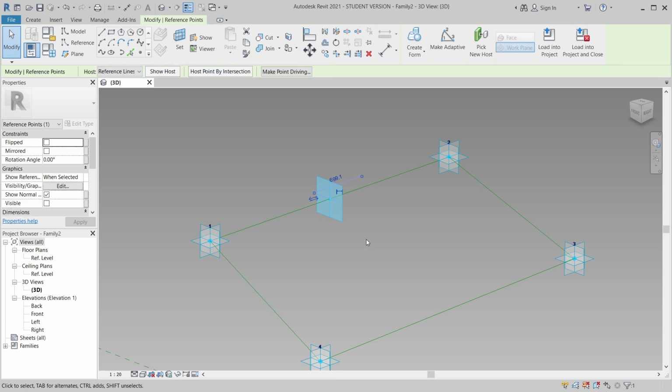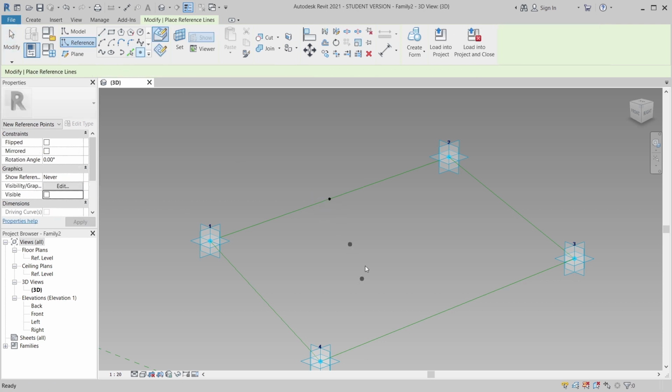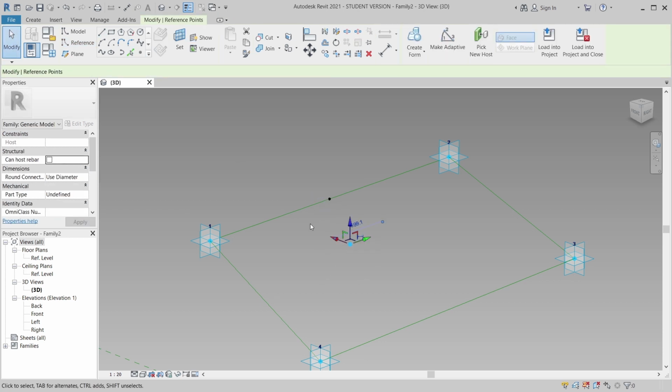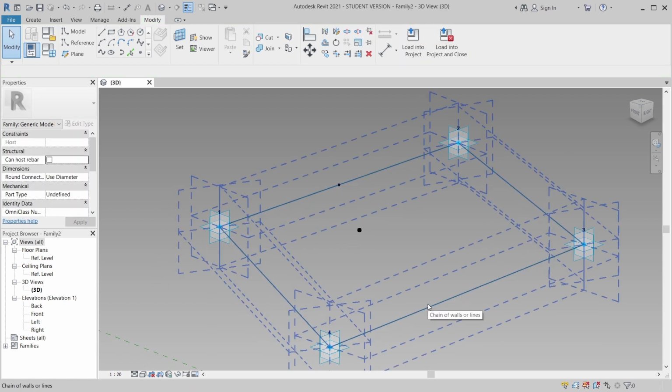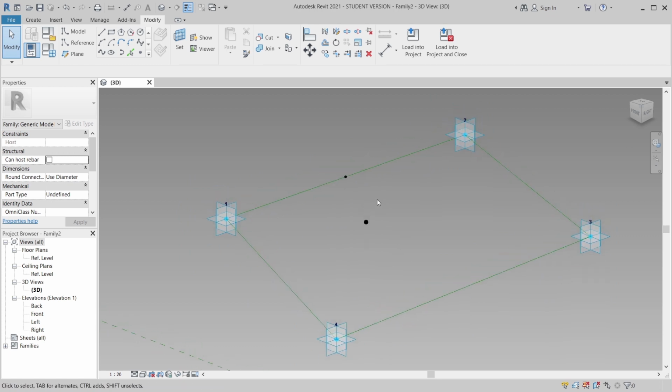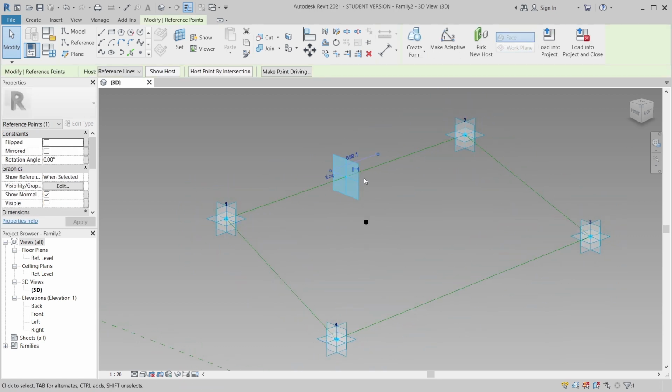First thing I'm going to walk through with you for this guy over there. It is different from our other option, because our first option for placing point is only for reference point. As you can see here, it is a reference point, and another guy for number 1 until number 4 there is our adaptive component, and this guy over there is different from these first two. So what is different? Basically this one we just use for reference to create our exact structure and exact pattern that you want to create into your project.